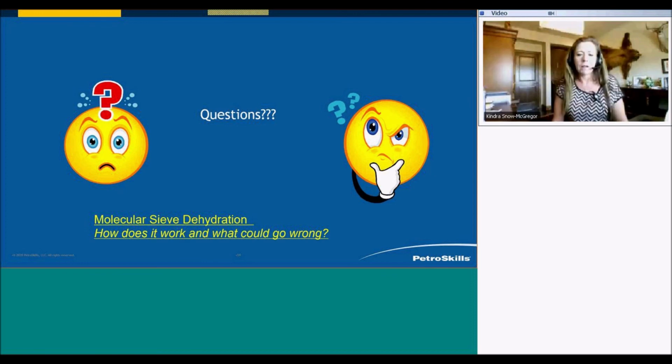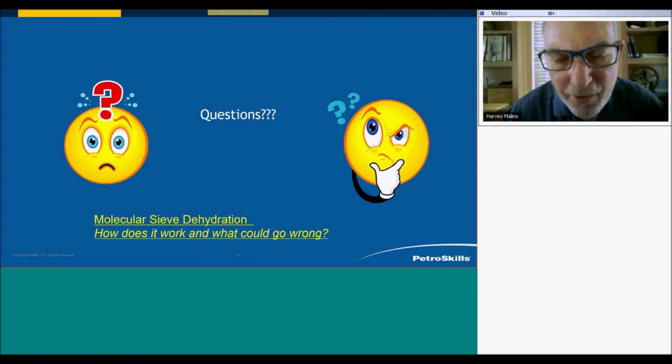Well, those are good comments because you are correct. Because the 3A has lower water capacity, you're going to need to turn the beds around quicker. So you're going to need more regeneration time. You might have to revamp your regeneration circuit.